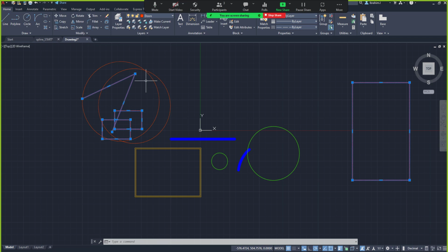That's to tell you about this select similar command. You'll be expecting that you are trying to select a group of a layer. Are you with me? When you are selecting similar, it will only select this. You know, rectangle is a polyline, right? Yes. And then other lines that are drawn with the same property, they will be selected. Can you see that here? That is what is happening here. This circle is on the same layer as the selected objects, but it's not selecting them because when you select similar, there are parameters that AutoCAD will use to choose the objects that you want to select.